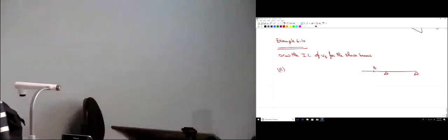With the results on load combinations in the STAAD software, what diagrams do you want? What do you need in a report from STAAD? Okay. I need the independent force diagrams: the normal force diagram, shear force diagram, and the bending moment diagram, and I need to have values on that figure.